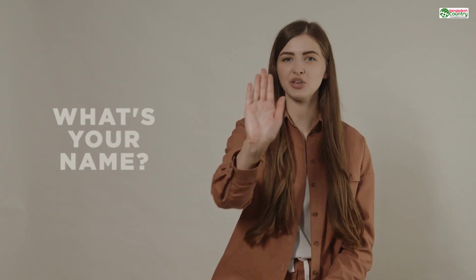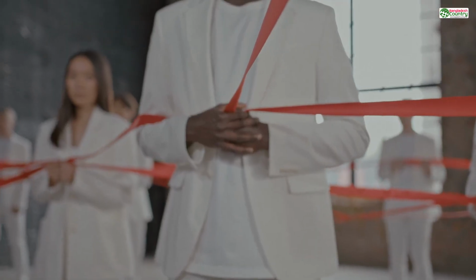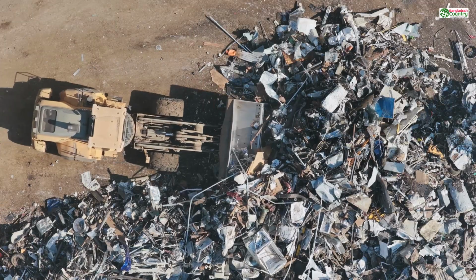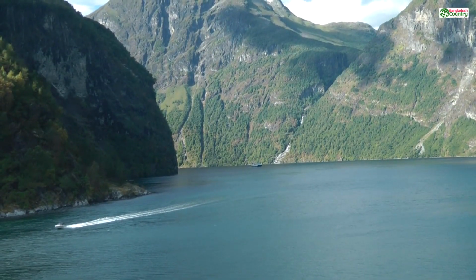Now, you might be wondering why these specific numbers. 0.1, 0.2, 0.3? It's not arbitrary. It's tied to the physical hardware of the printer itself, specifically the nozzle, the tiny metal tip where the melted plastic comes out. Most standard 3D printers use a nozzle with a 0.4mm opening. A good rule of thumb in printing is that your layer height should be somewhere between 25% and 75% of your nozzle diameter.